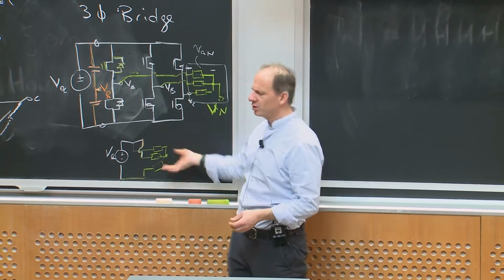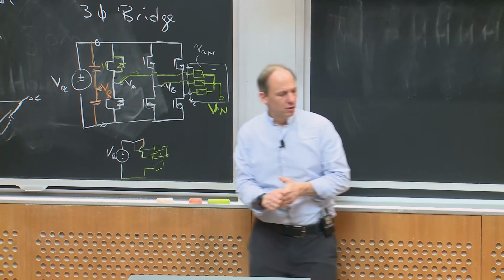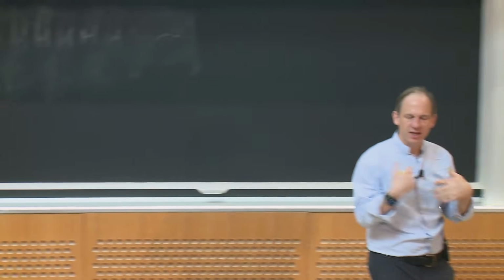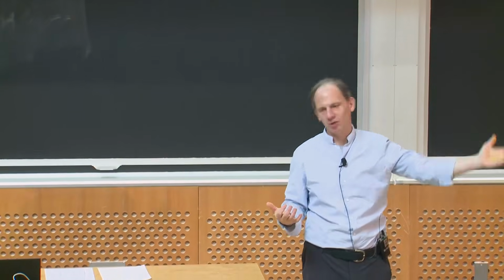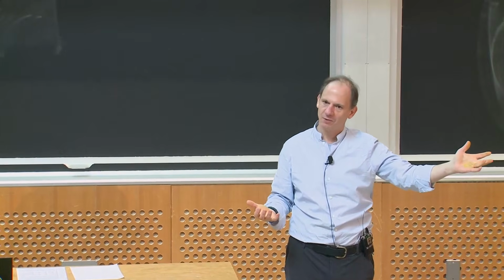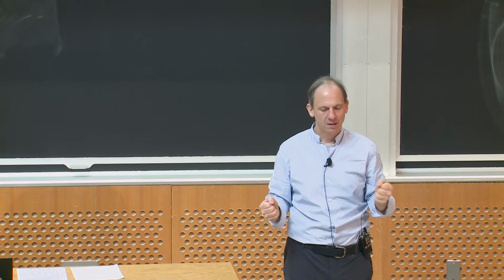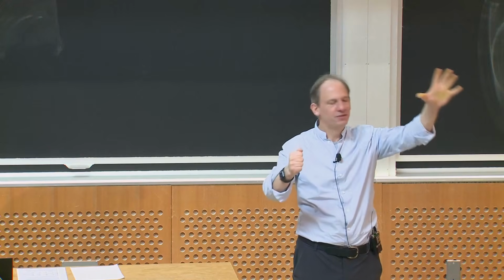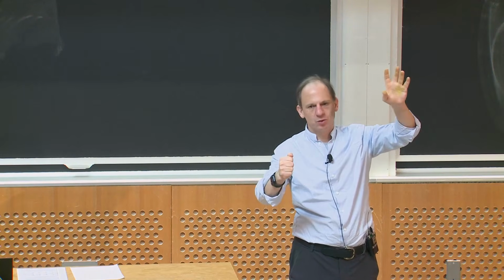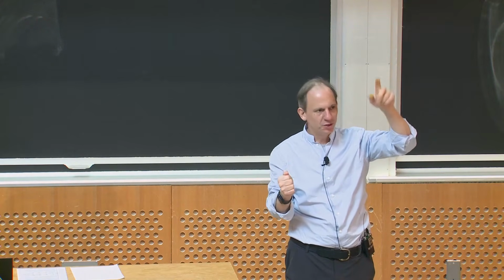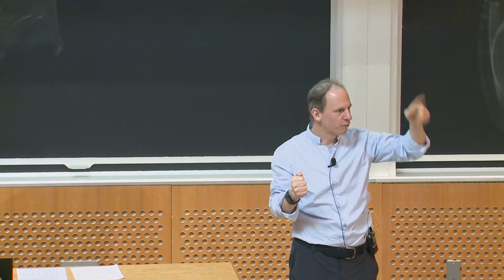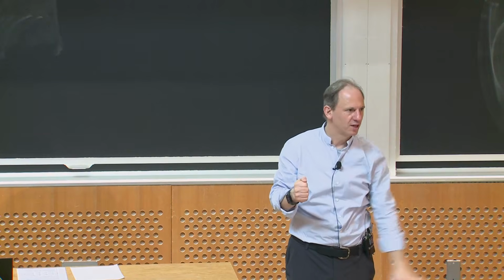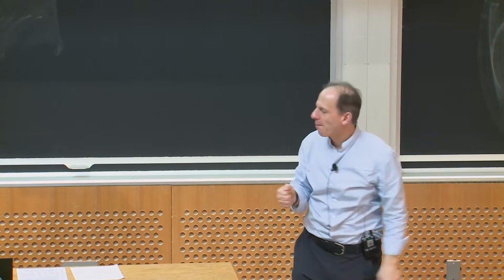Okay, so that's the way you tend to think about it. So one way I could run this is very much like the inverse of the diode rectifier I talked about last time, right? If you remember last time, as the AC waveform drove the diode bridge, the individual diodes turned on. If you remember, it was like 1, 2, 2, 3, 3, 4, 4, 5, 5, 6, 6, 1, right? So it just went around in this 6-step pattern, okay?